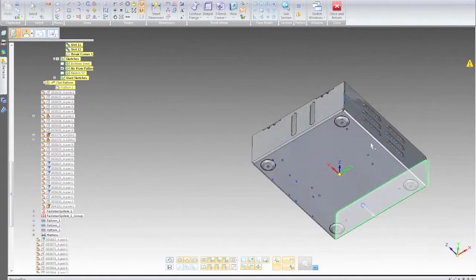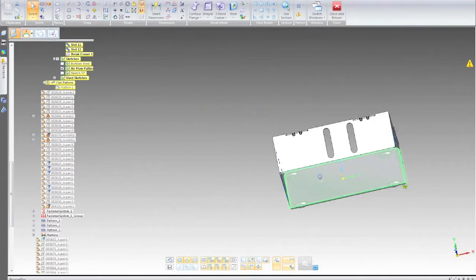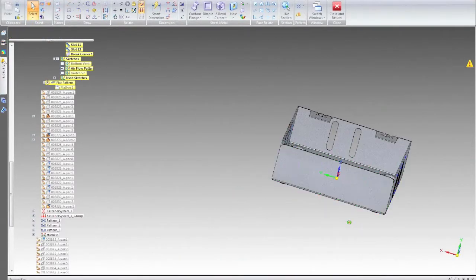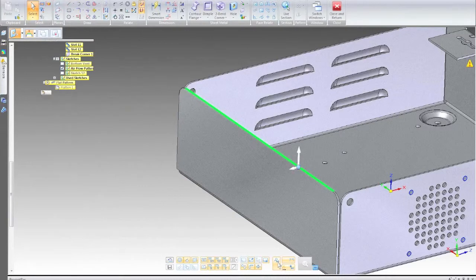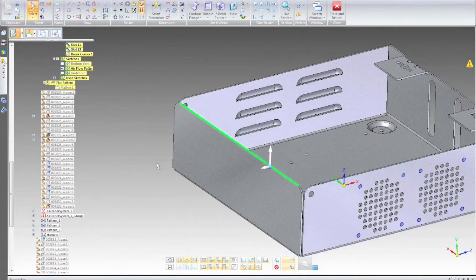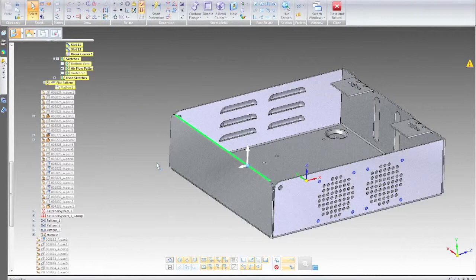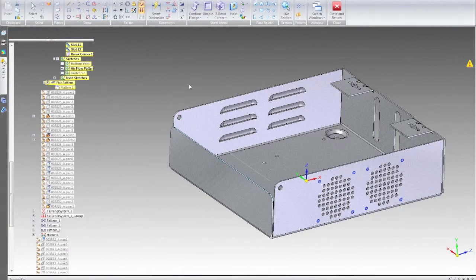So as soon as, there we go. Go ahead and grab this face right here. We're going to suspend our live rules because we don't want the other side to come down. So we'll drag this down, we'll say about 16, there we go, about 16 millimeters. Okay, so now I've bent that down, now I have clearance for my lid,